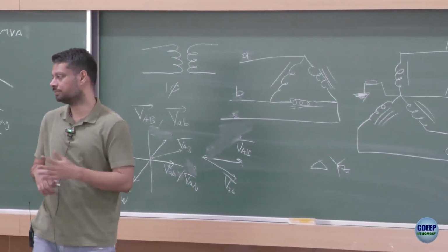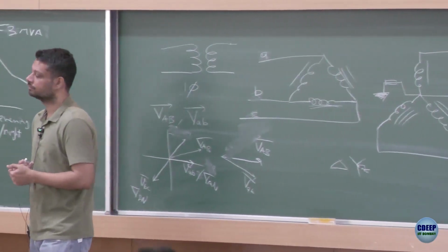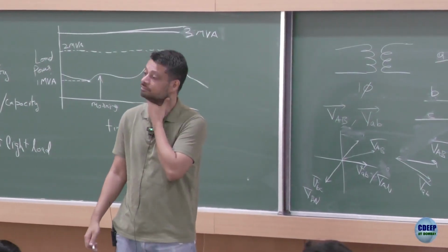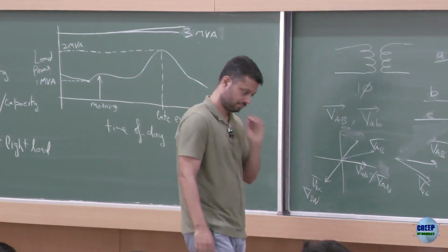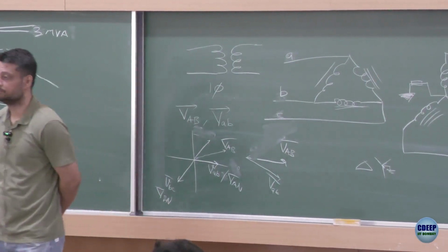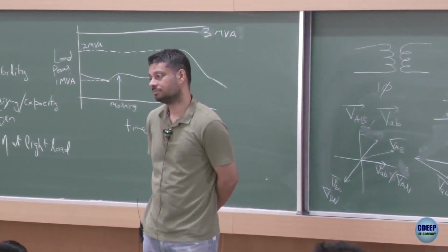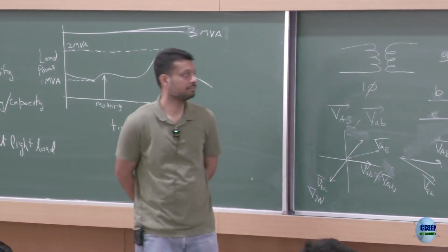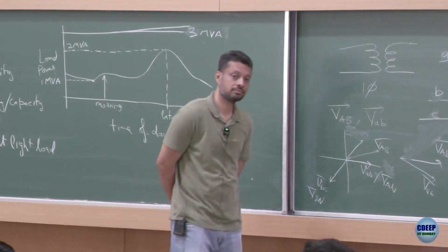So question is why? I guess on the load side we want a neutral wire. Okay. Because we don't supply phase, we supply phase neutral, most like low loads outside of like ACs or large. Okay. Single phase, so we want a neutral for the load. Okay. We will use the star in the load. And in the supply, we don't need an extra wire that is also large current, so we'd rather just have a delta connected thing.